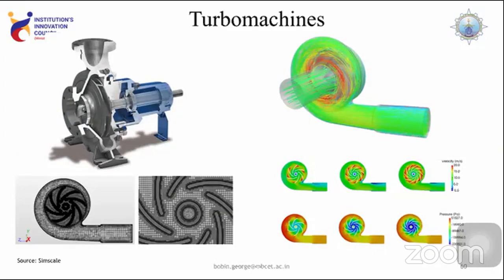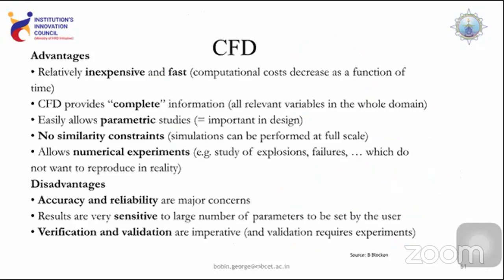By employing computational fluid dynamics, you don't need to construct an arrangement, like placing whether it is a radial curved vane or a backward curved vane, and how the volumetric flow rate can be measured. Similarly, how the pressure variation can affect the increase in flow. Again, turbulence will come into the picture as well as swirl. We have to model that with the help of commercial solvers, especially SimScale. This is one of the most widely used solvers when it comes to turbo machinery now. So I hope you got an idea about what the advantages and disadvantages are.